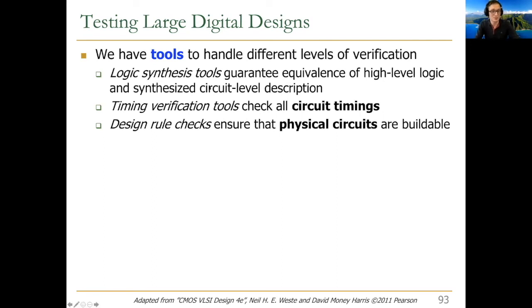Logic synthesis tools guarantee equivalence of high-level logic and synthesized circuit-level description. So basically, you write in a hardware description language, you give it to a tool that synthesizes it, and hopefully somebody verified it formally or with some other testing methods that it's guaranteed to be correct. That's what you're relying on over there. Timing verification tools check circuit timings, and sometimes your synthesis tools actually do that also. In fact, you will see that they will, but they may not be perfect in this case.